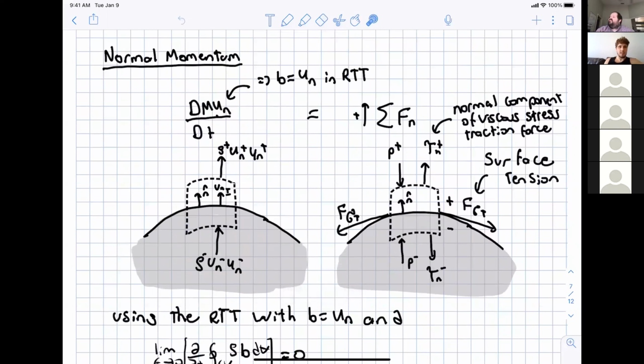Okay, well, I'm not repeating everything I just said for the past 10 minutes. So normal momentum, conserving forces and accelerations as normal. The only thing that you probably haven't dealt with in fluid mechanics is the surface tension forces. And so just recall that the sides of the control volume tend towards zero, but surface tension exists only on the surface. So even though the sides are tending towards zero, the surface tension force will still be in there. If you're doing droplet combustion or spray atomization, you do need to consider surface tension forces. They can be very important for some applications.